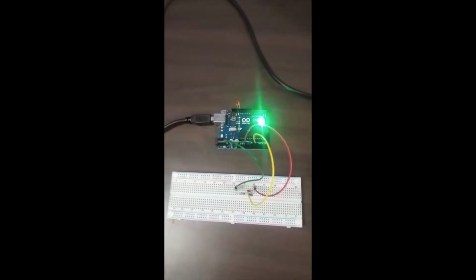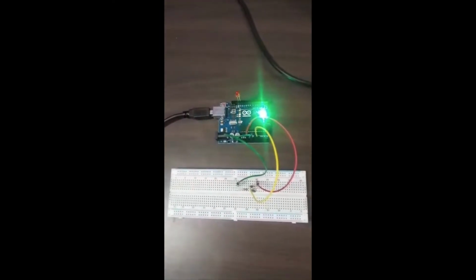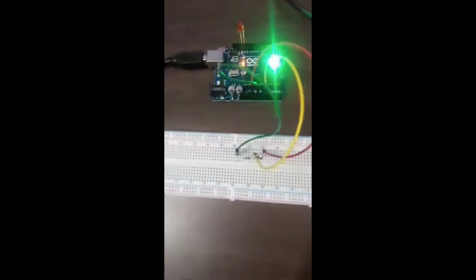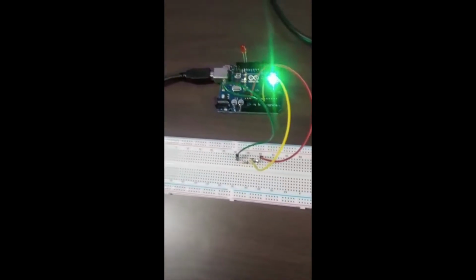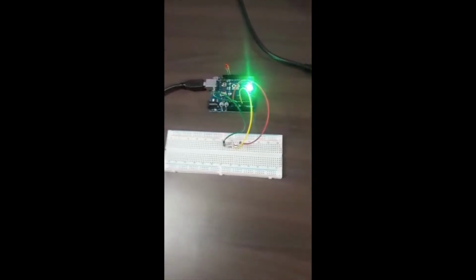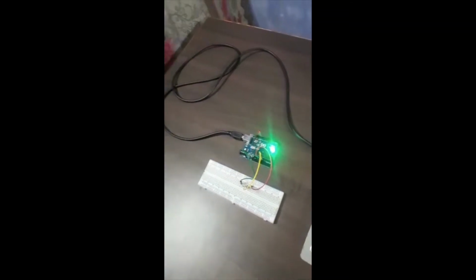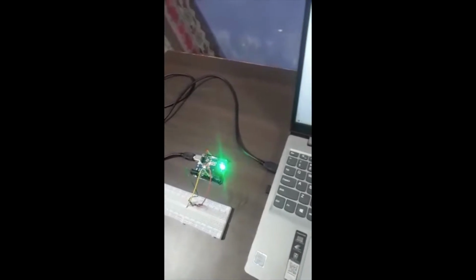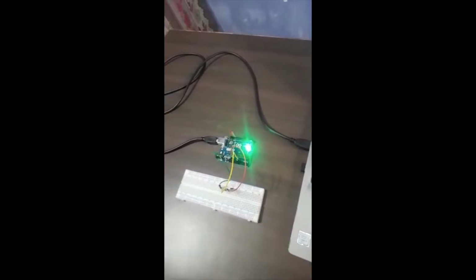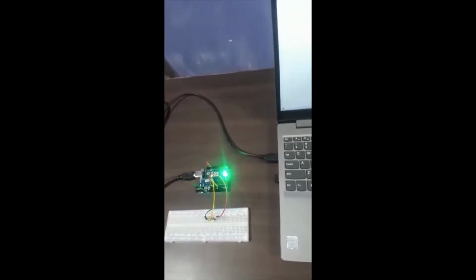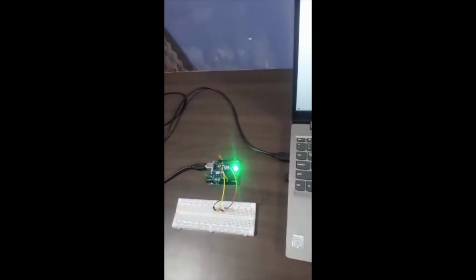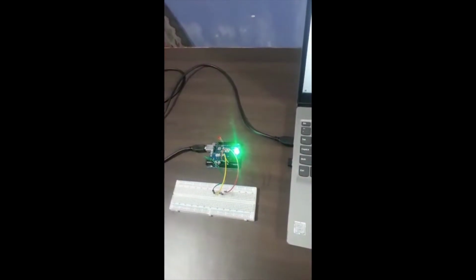Now I have completed the modeling part and uploaded the code to be executed in the Arduino. Now I will demonstrate the working of this model. So for varying the light intensity at the LDR, I will use a mobile torch, which is approximately a point source. And we know that the intensity of light at a distance r from the point source varies as 1 by r square. So by varying the distance between the LDR and the point source, we can vary the intensity that will be recognized by the LDR.